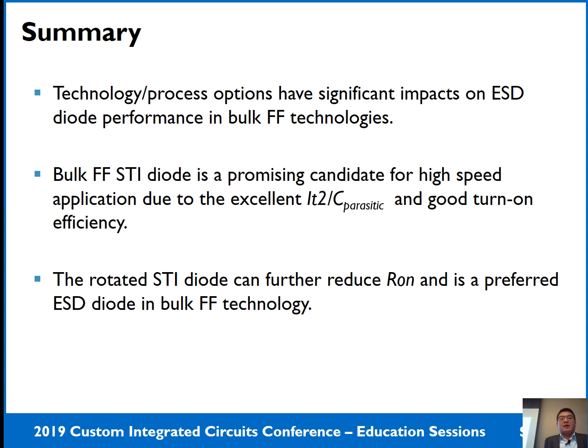Also, the STI diode in bulk FinFET shows almost no overshoot, meaning it can be turned on very fast, like the gated diode. Finally, I showed this rotated STI diode. It can further reduce the R-on, so it's a preferred ESD diode in bulk FinFET technology.